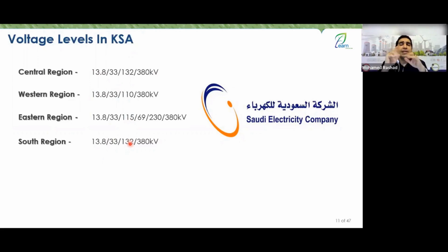When we started connecting these regions together, you had 2 things. Firstly, the distances between them were already far over 300 or 350 kilometers. So you needed to raise the voltage even more to reduce the current, thereby reducing losses and voltage drop. The second thing is that the voltages they had were different. So you couldn't just connect these voltages together without causing a short circuit.